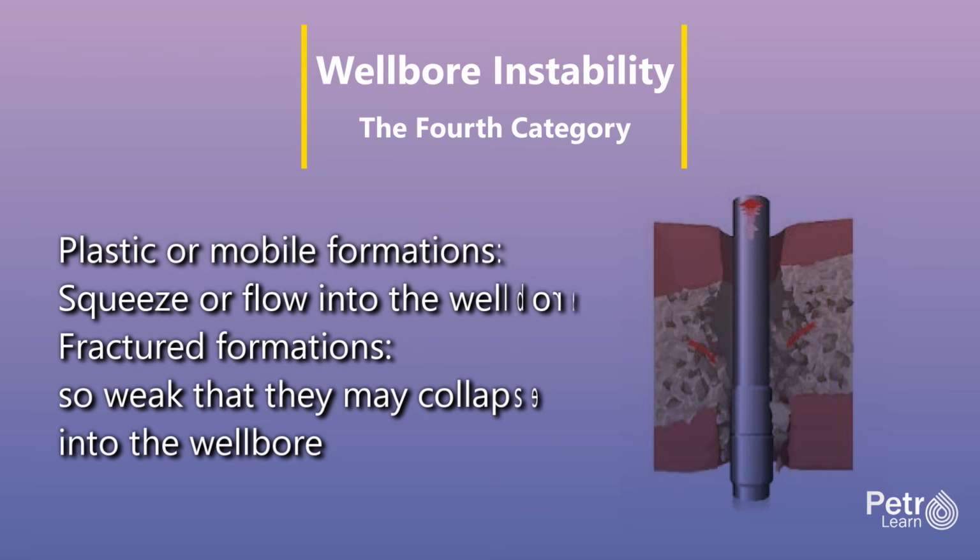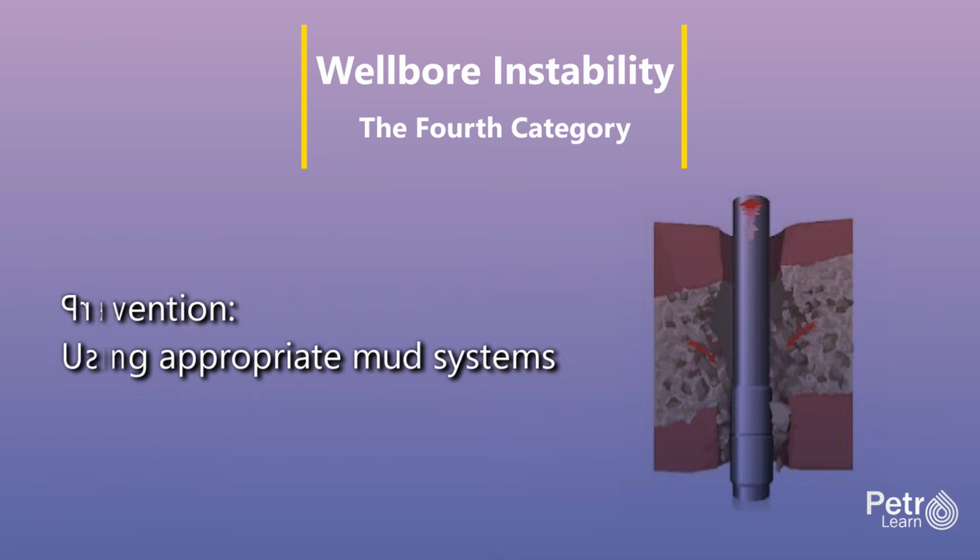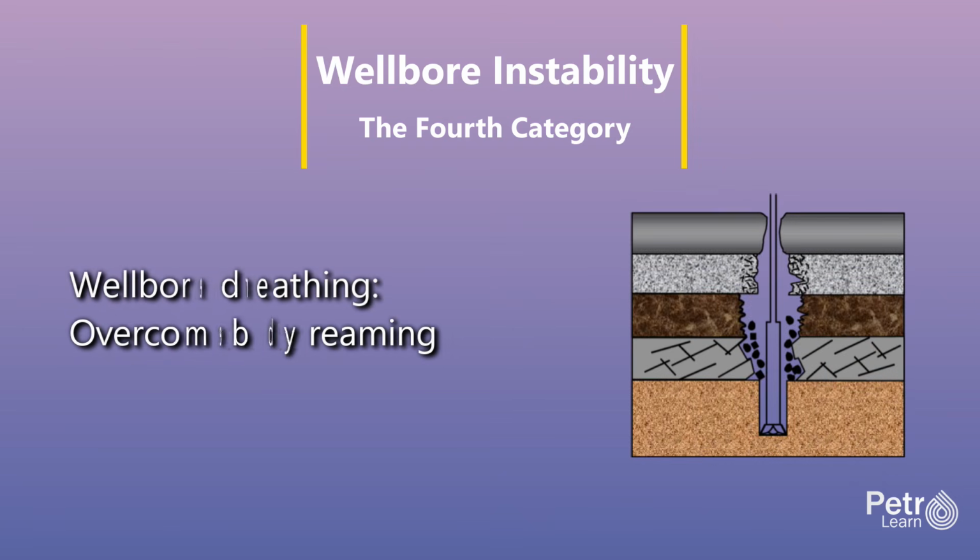Fractured formations may cause lost circulation or may be so weak that they collapse into the wellbore. Prevention involves using appropriate mud systems, such as oil-based mud or specially inhibited water-based mud for reactive shales, maintaining proper mud weight to support the wellbore, but not so high that it fractures formations, and drilling through problem zones quickly to minimize exposure time. Wellbore breathing is a phenomenon where the wellbore diameter expands and contracts in response to pressure changes during connections or trips. This can indicate weak formations at the verge of fracturing or collapsing.